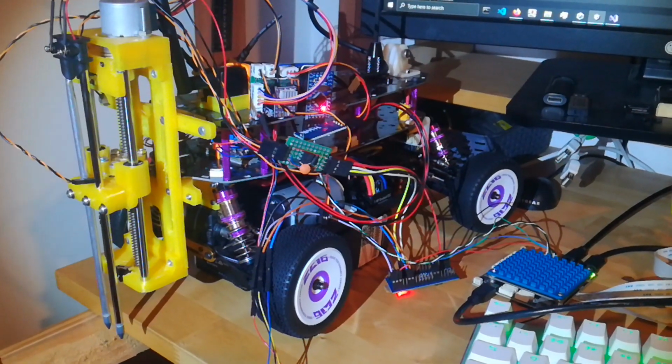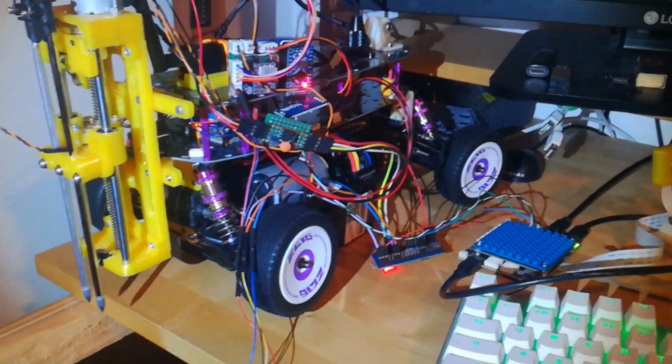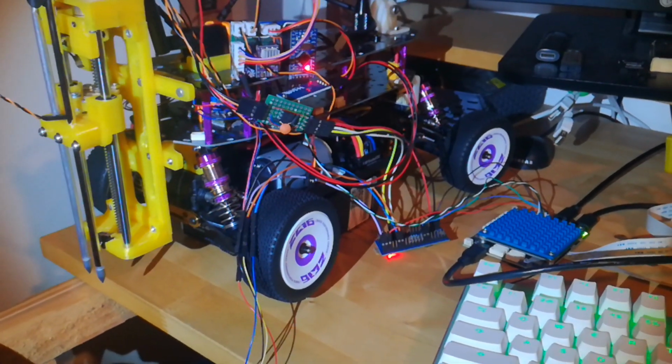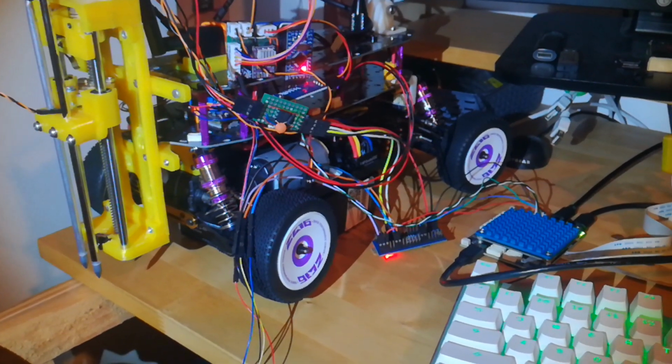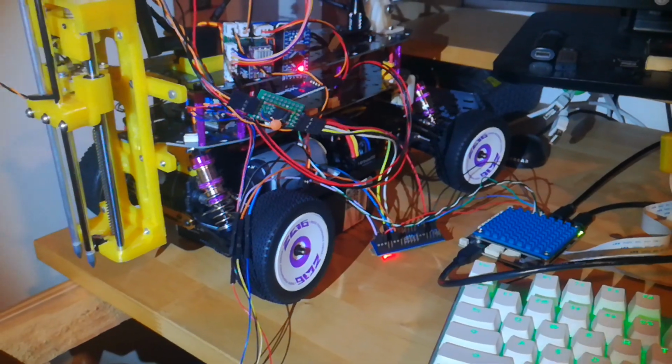The soil sensor then samples data from the soil. This data is in analog voltages which are converted to digital by an acquisition hub. Right now this is an STM32 board which is down there. This STM32 connects to the NavQPlus over serial connection where the NavQPlus can read the sample data.